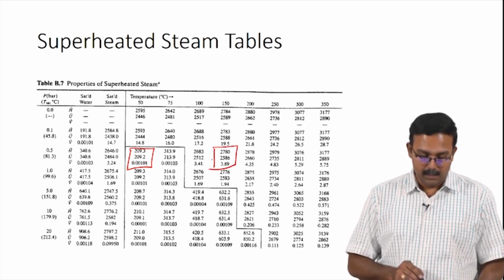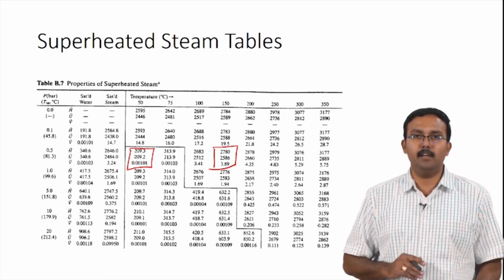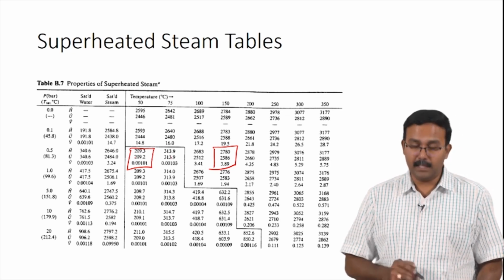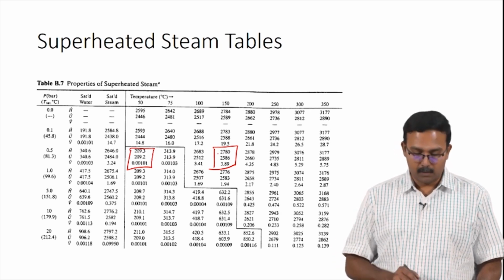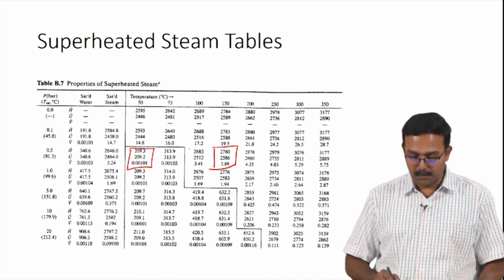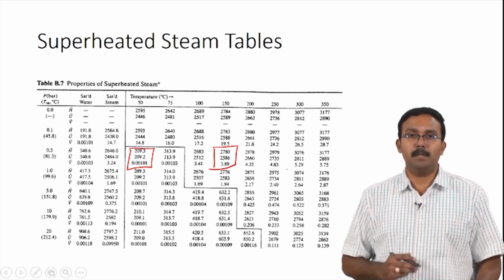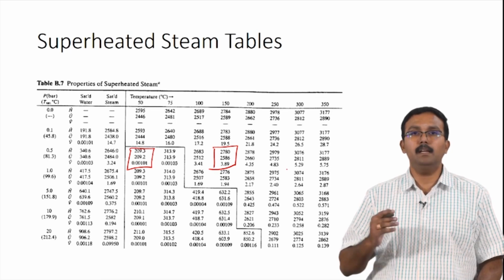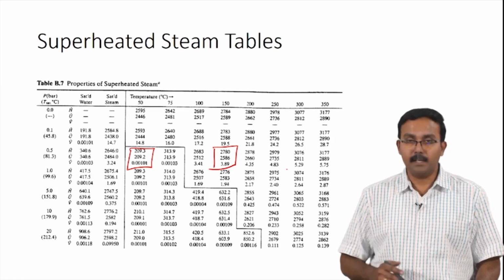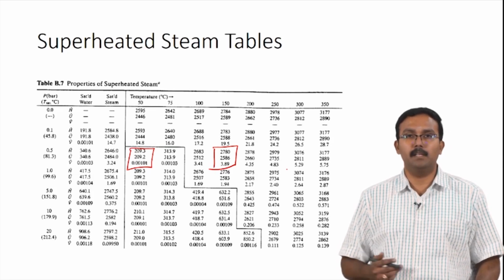At 50 degrees Celsius the water exists only as a liquid, not in any kind of equilibrium, and at 75 degrees Celsius it will again exist only as a liquid, and at 150 degrees Celsius it will exist only as vapor. Whatever conditions in which water exists only as liquid is covered within this step shaped box. Everything outside of the step shaped box is a vapor condition. Within the box you have only liquid, called subcooled liquid or simply liquid, and outside of it is called superheated steam, where you have only steam and it is not in equilibrium with anything.